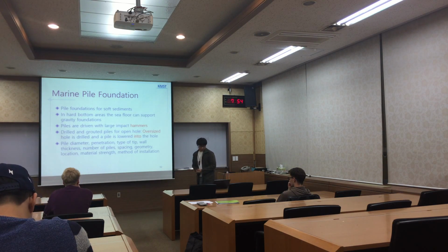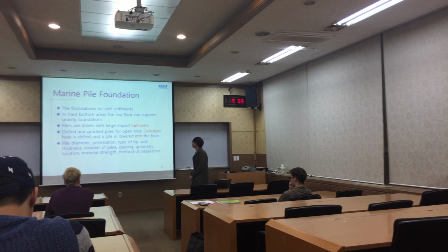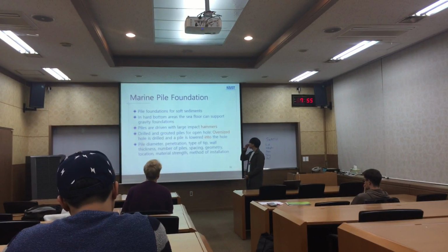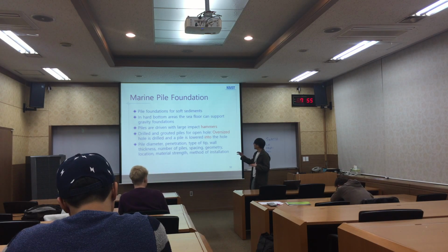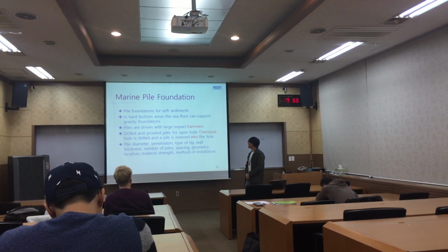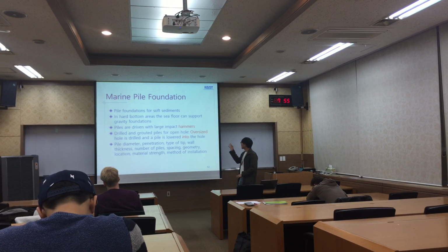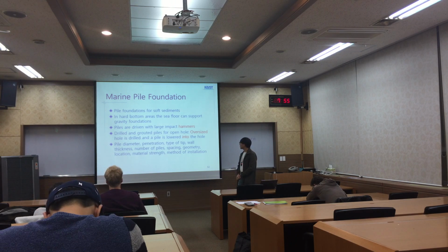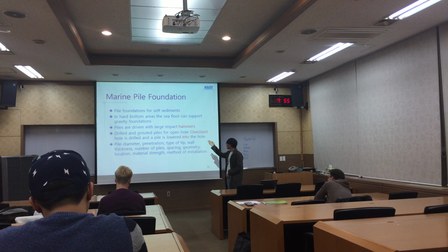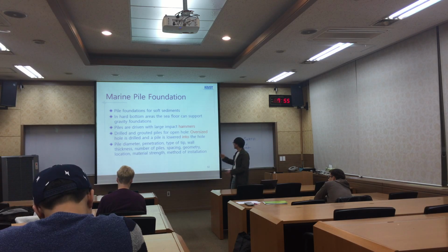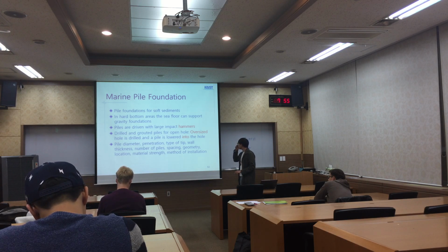So marine pile foundation is for soft sediments, while in hard bottom areas, as we see in the video, the seafloor can support a gravity foundation. So when we are driving piles, we use large impact hammers, as you can see, and some drilled and grouted piles for open hole.